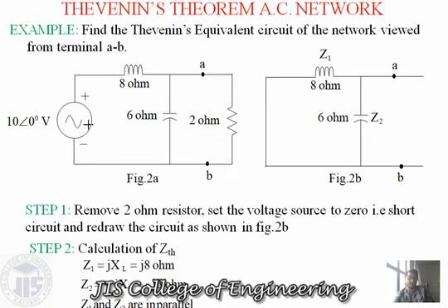And as there is a source, this is a voltage source, obviously it's an AC voltage source, and we know the voltage source has internal resistance or internal impedance that is also negligible. So we can replace these sources and we can short the terminal, right? As we have shorted the terminal, and the load impedance or load resistance that was there, we have removed it. So we will look from this side to find out the overall impedance of the circuit, to find out our ZTH.